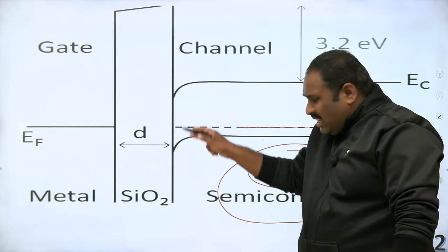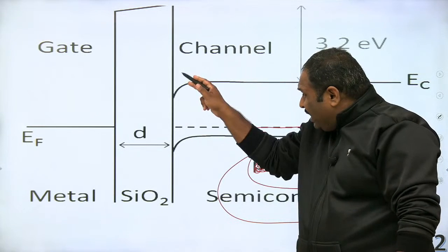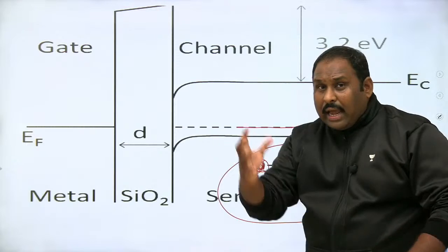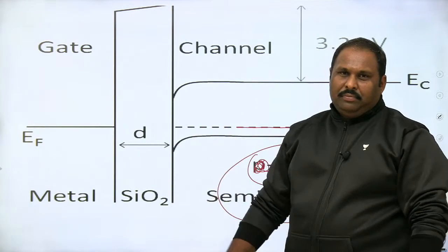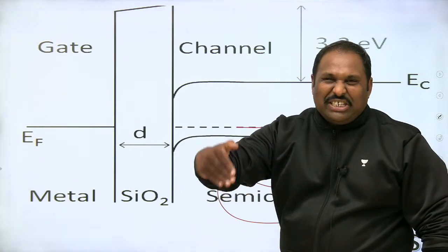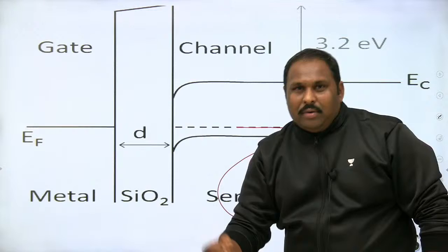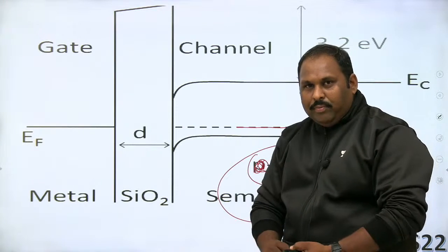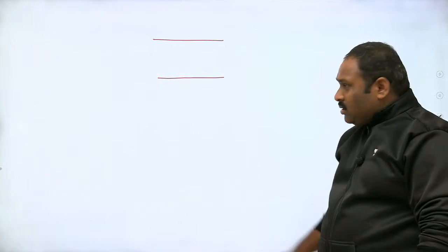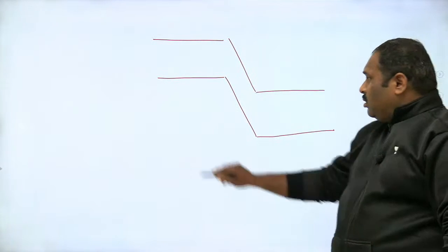What happened here then? You find a lot of negative charge coming, or electrons coming, and lowering your potential. Whenever you have negative charge, electrons or N region, you have a lowering of your potential. That's why even in a diode, the P region is shown with higher energy levels and the N region is shown with lower energy levels.